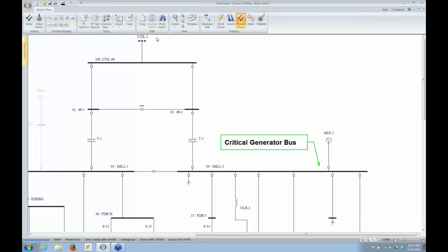And so it needs a source, at least one source, that it can use to balance out the equation. It's kind of the slush fund for the PowerFlow. And we call that a swing source. And you might hear it referred to as a slack source in some literature. Basically, to run the PowerFlow analysis, we need one source that's modeled as a swing source. Normally, that's going to be your utility source. If you only have one source, then it's a moot point.